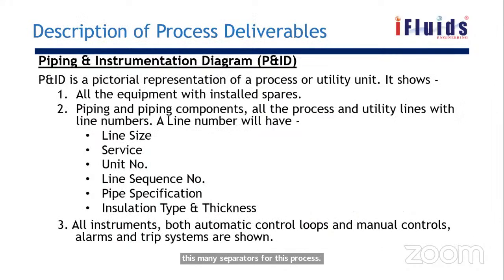And then the P&ID diagram. We talked about the P&ID, piping and instrument diagram. This will be going as an input to all the other disciplines: instrument, mechanical, piping, all the teams. The P&ID will be covered with whatever data you calculate. Like you will be calculating the line size, and that data will be put in the P&ID: 4 inch, 6 inch, 10 inch, 12 inch, 14 inch, like that.